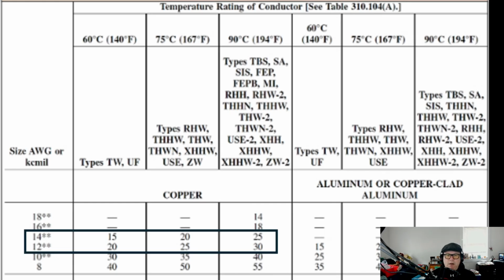You got to understand, all the way up top doesn't tell you what this is for. It could be open air, it could be anything, we don't know. I'm just showing you this is what you look for. So look up top, you'll see it says what it's for. Then you look down here, look at your amperage. Remember, you only can use 80% of this. And make sure you install it right. Make sure you have enough room in your pipe. You don't want overheating, because it can lead to possible injury or death.